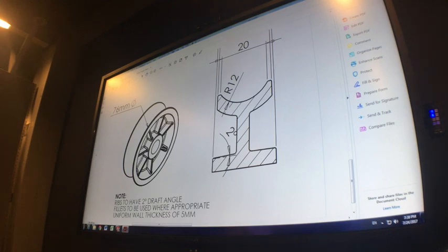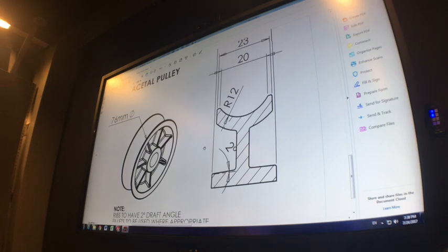which are these ribs. Those ribs have fillets on them, and once you've done one, we do a circular pattern to do the ribs, and then we mirror it all to the other side. So there's a series of steps that makes it really easy for it to be adaptable later, so we can customize it and change any dimensions if we need to. We'll also look at a little bit of draft angle to see how that works, and how to add fillets in a couple of different ways.